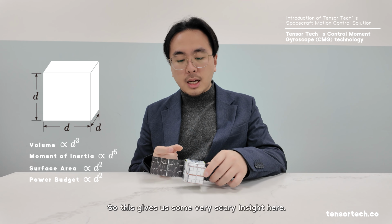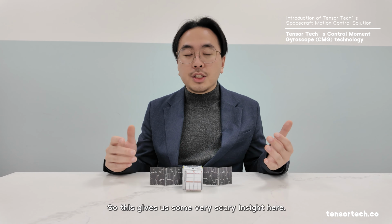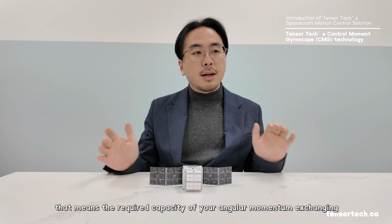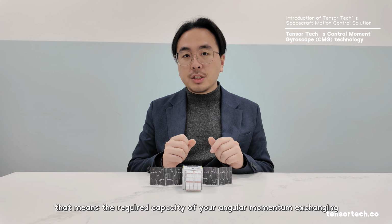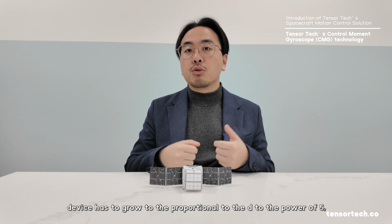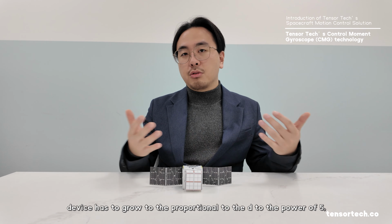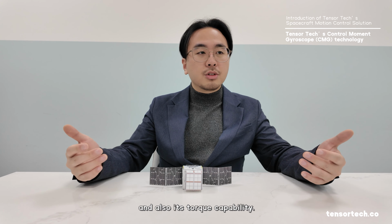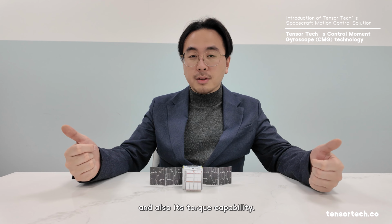So this gives us a very scary insight: whenever your satellite gets larger, the required capacity of your angular momentum exchanging device has to grow proportional to d to the power of 5, including its angular momentum capability and its torque capability.